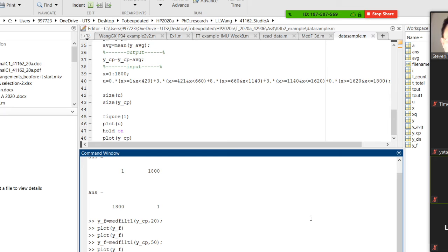You still have lots of choices for filtering and signal processing. It's not just what we teach. Sometimes the filtering is based on the noise property. If the noise is not related to frequency, the methods from before, stage one and stage two, will not help too much. But unfortunately, in most cases, the noise is related to frequency.